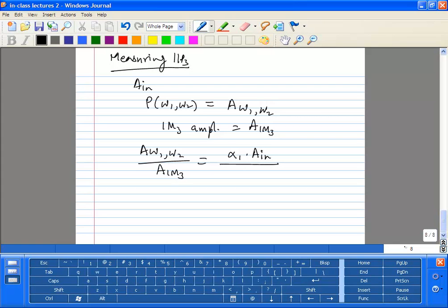Remember, when you measure IIP3, usually you give very small signals. You don't want to move into the compression region. So when you design your LNA or something in the lab, in your simulation, if you end up choosing a point where it has already started compressing, you will get a different value of IIP3. So just make sure, be judicious in your choice.